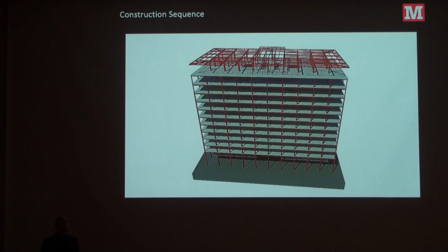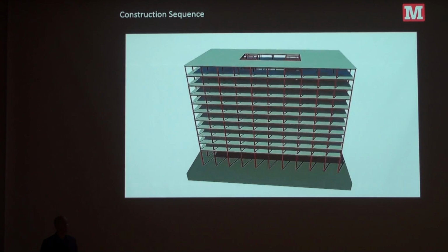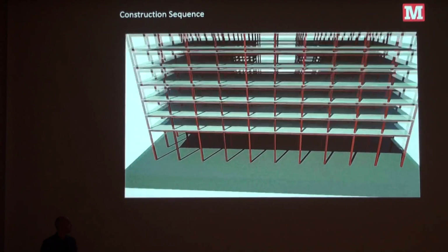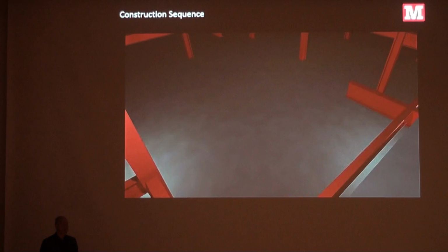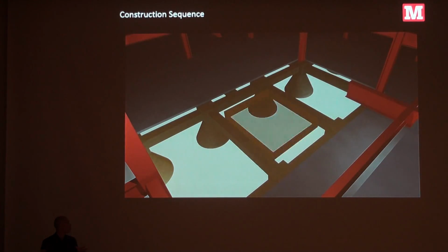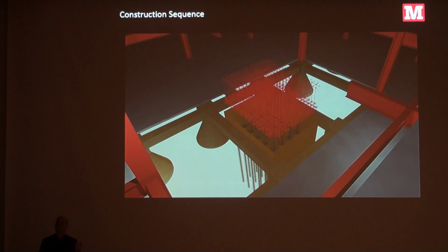So this is the original 1960s frame. There's a removal of the old penthouse, opening up of the floor. This element is 30 feet by 30 feet. It's about 18 inches thick for the concrete, so it's heavy. So we've got micropiles at the base. There's its foundation, and that is the pin.